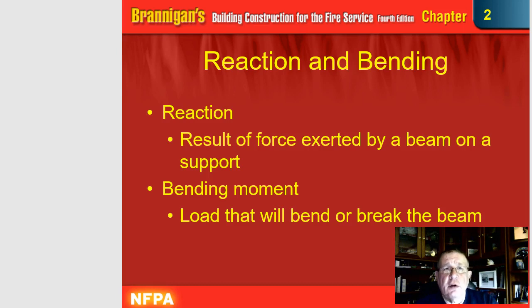So it goes to tell me when you have a temperature, steel starts at about 800 degrees where it starts softening up. So when you're looking at a fire of 1500 to maybe 2000 degrees, steel's doing one thing. It's stretching and it's twisting at the same time. So the reaction and bending becomes a very important part under fire conditions.